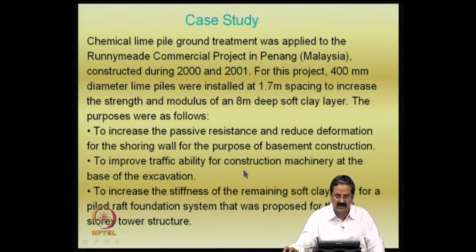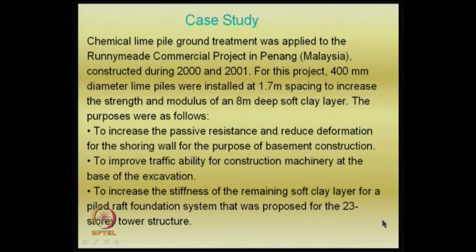So, people use the lime treatment, sprinkle lime, to increase the stiffness of the remaining soft layer for a pile raft foundation system that was proposed for a 23-story tower structure. You can imagine that the height of the structure is 23 floors, and you are looking at the improvement of the bearing capacity.